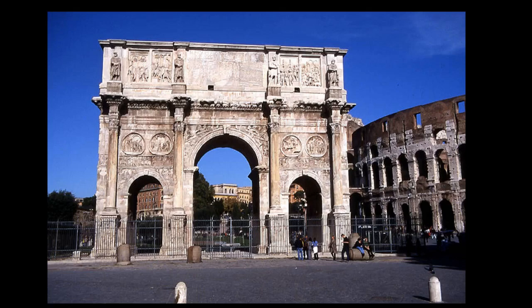So the column ends here, right? So here's the main element that gives the whole proportion of the system. That's the lower diameter of the column, and then the column should have a proportion roughly around 1 to 10, so a height of 10 compared to the lower diameter, and the capital should have a height of 1. So that's the main element, and it repeats itself like 4 times, and it's built directly in front of the wall, so it doesn't carry anything. The wall carries the load, same as the drawing we saw before.